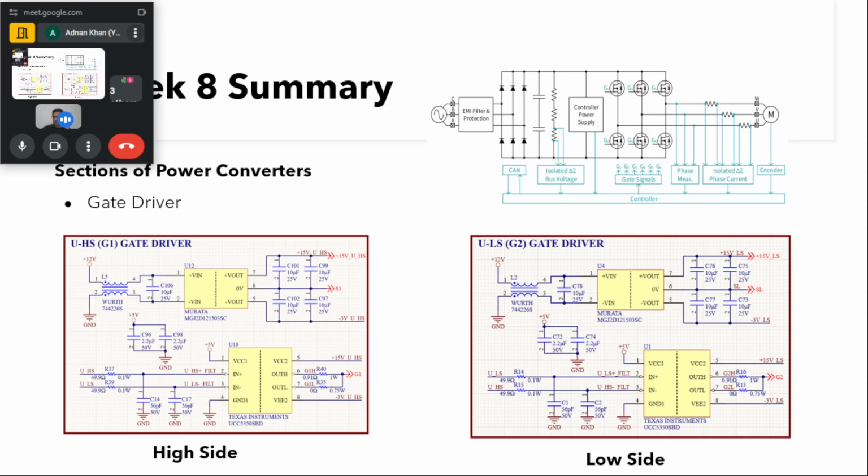We had to take care of the floating supply, and one of the ways to do that was to have the isolated supply, by which we can provide the proper voltage levels to give pulses to these high side switches. This was about the gate driver.